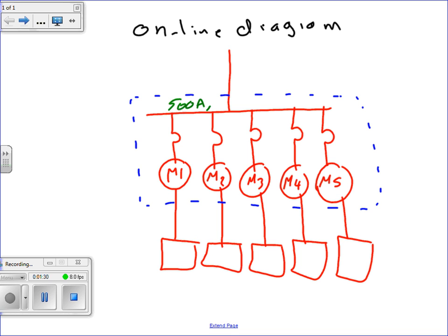You guys are going to size it. It's going to be a 240/120 volt system, right? 60 hertz. And the name of this panel is main panel. If you name the service panel, whatever, that's going to be the main panel box. It's typically a meter center that has all the meters inside it and distributes the power to all the equipment.